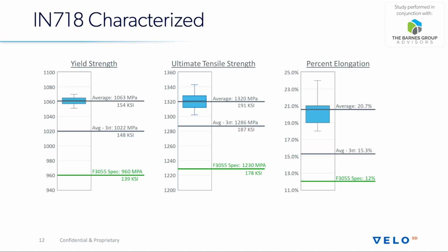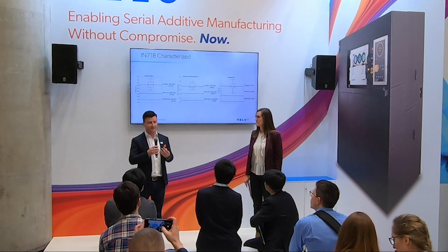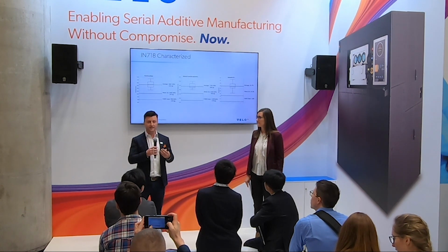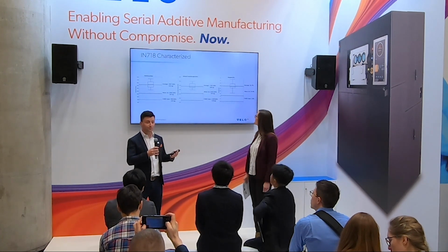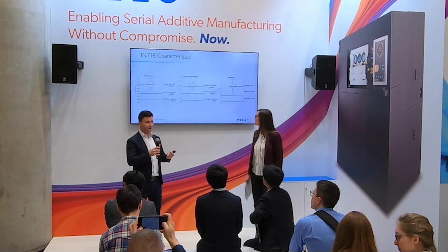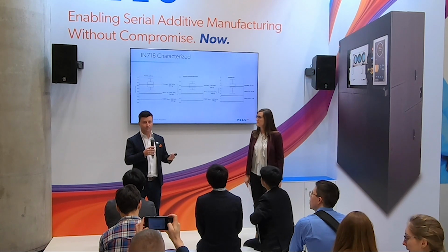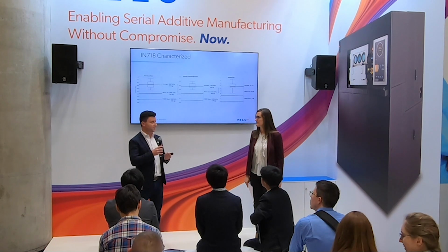The other aspect of this that's really important is statistical mechanical characterization. So looking at how stable the mechanical properties are across a full data set. In this case, we're presenting data from 5 different machines. So this is 10 different laser paths since we have a machine with 2 lasers. It's something like 100 samples, looking at how the statistics vary across the build plate, across builds, across machines, and across lasers. This is really important because it gives you confidence in what is really the third column that we're looking at, which is the stability, robustness, and repeatability.